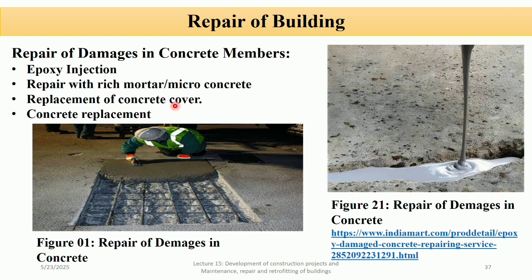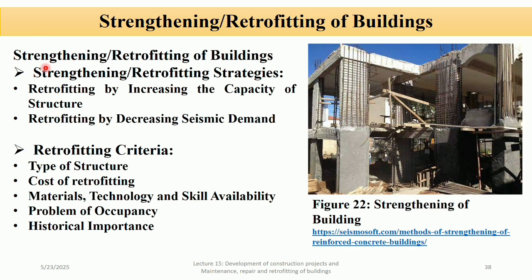So removal and replacement of the outer layer of concrete, meaning the cover that protects the reinforcement steel. Concrete replacement. In this, removing severely damaged concrete parts and recasting them completely using fresh concrete, you can see in the figure. Now let's discuss strengthening and retrofitting of building.